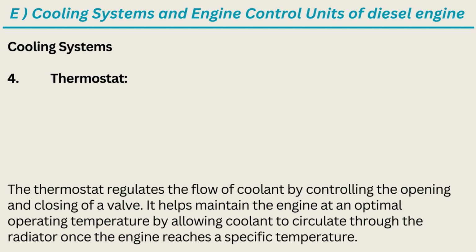4. Thermostat. The thermostat regulates the flow of coolant by controlling the opening and closing of a valve. It helps maintain the engine at an optimal operating temperature by allowing coolant to circulate through the radiator once the engine reaches a specific temperature.